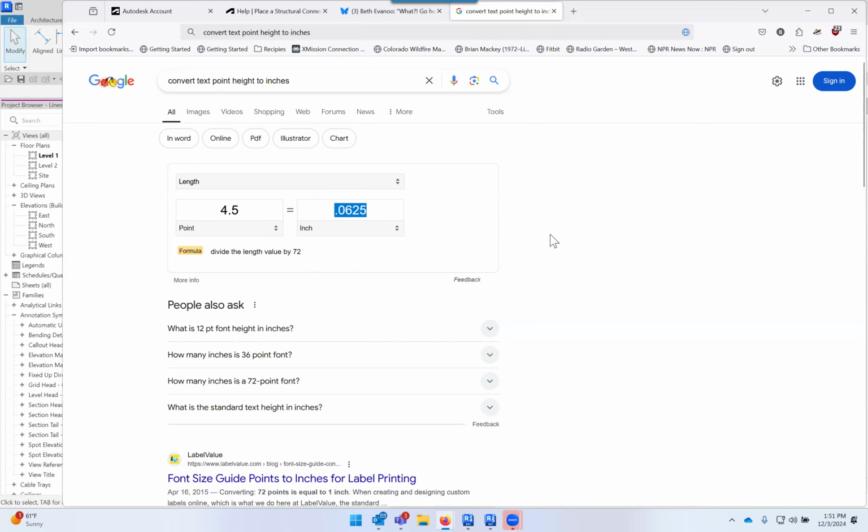So you've got to go through and do all of those conversions in Excel and make that stuff in Excel the right height for Revit to understand. That's the biggest thing for me. And ironically, I think this needs to be a higher decimal accuracy than this. So it's got to be like, oh, this is technically 4.5016, and it's not exactly the same as what you see in Revit, so Revit generates its own style. That's the big thing for me when you're really trying to get into it.